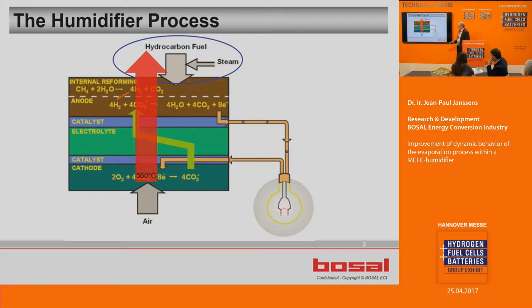So the cathode flow has here a temperature of 560 degrees. And that is used to heat up water at 15 degrees C and the natural gas and mix it up to 400 degrees C. Now, that means that you need a counterflow heat exchanger. So you have to heat up both. You have also the latent heat, and you want to reach this temperature. And then we speak about effectiveness. So if the effectiveness is as high as possible, 100%, then this temperature reaches this temperature. Otherwise, in this relation, you have a lower effectiveness.